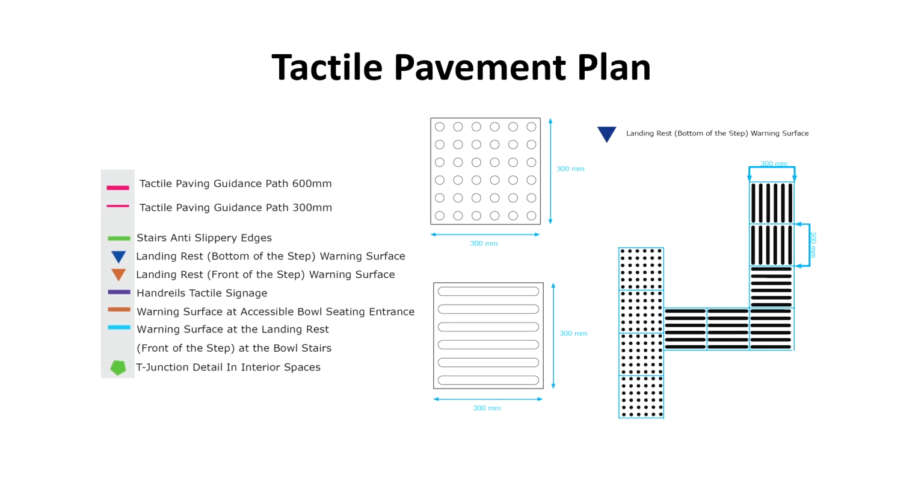After that, we create a layout that outlines the placement of the tactile pavings in relation to the surrounding environment. This includes specifying the dimensions, the patterns, and the color of each of the pavings.